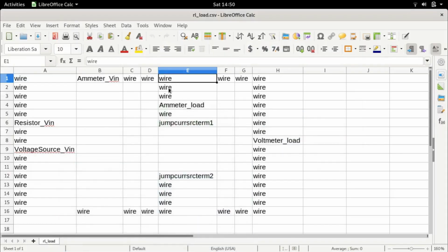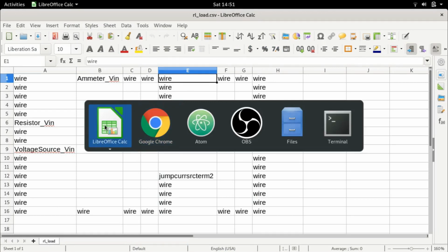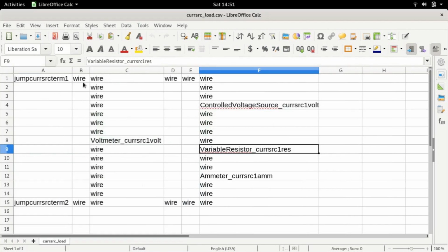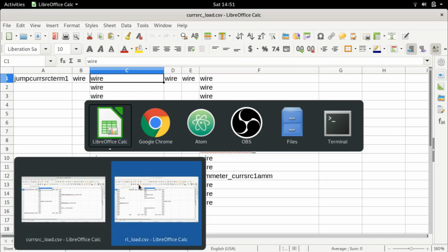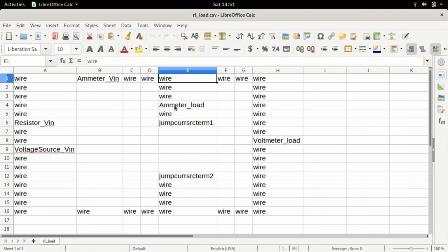You see here, there is this ammeter load, which is where we had the variable resistance and the variable inductance. Since we had removed the variable resistance and the variable inductance, and we had later connected this current load, there is a 0 resistance branch from this node until our load circuit. So for example, from this node to the node which I just mentioned, there is a 0 resistance branch, and that is a bug. So what I'm going to do is delete this, bring it down, and here I'm going to put in a resistor.